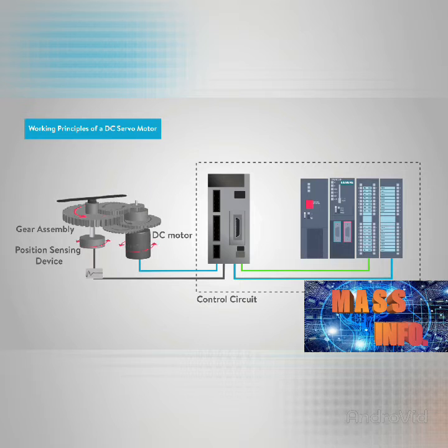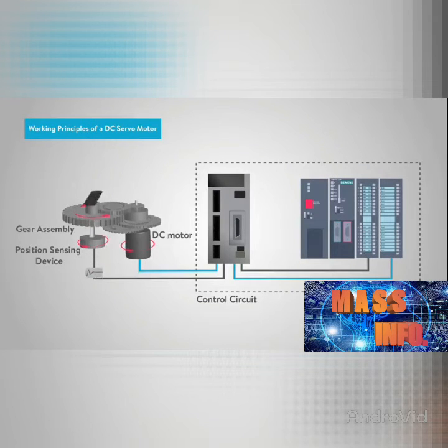The feedback signal sensor is normally a potentiometer that produces a voltage corresponding to the absolute angle of the motor shaft through the gear mechanism. Then, the feedback voltage value is applied at the input of the error comparator amplifier. The amplifier compares the voltage generated from the current position of the motor, resulting from the potentiometer feedback, to the desired position of the motor, producing an error of either a positive or negative voltage.